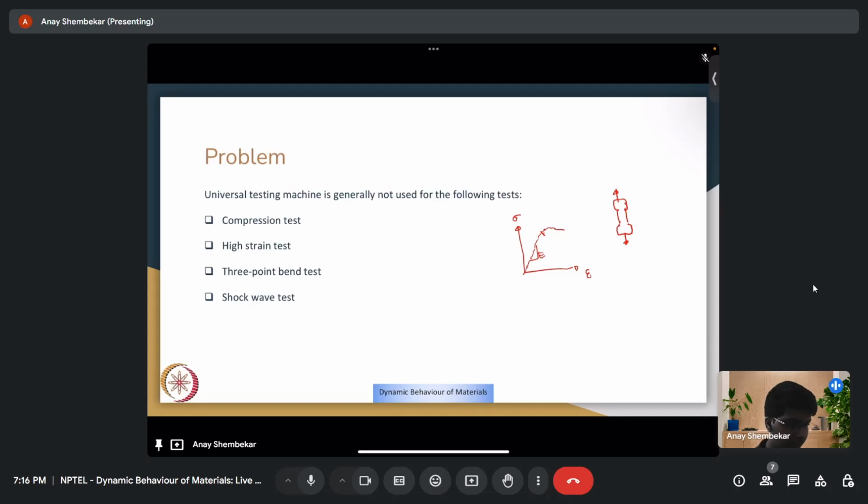Then you would have a necking region somewhere here where the cross section becomes very small, and finally the material would fail. The UTM is the preliminary analysis that we do in a lot of undergraduate mechanical, civil, and even aerospace labs, so I'm guessing that you are familiar with it.